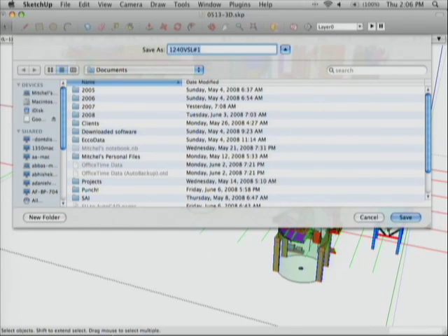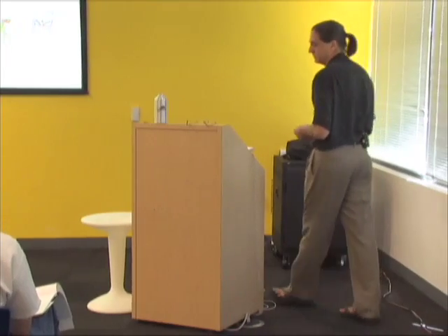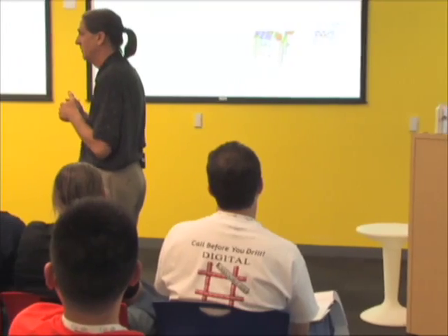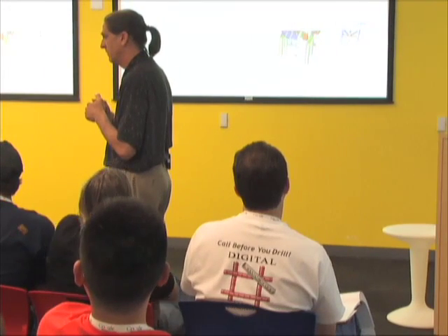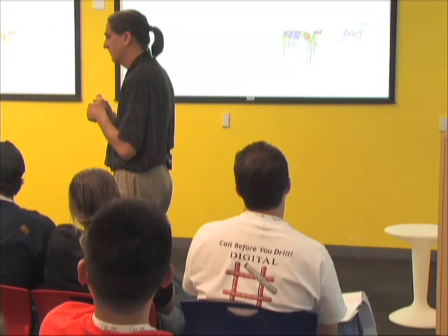The only point with components like this is that they come into 0,0,0 in their own little model, or the component axes shouldn't ever be changed, because it will come in a different place back into your model. You can change it, but then you've got to remember that. If you take that component out to another file, and you copy and paste it using paste in place, it'll actually paste it to where it should be in the model when you bring it back.